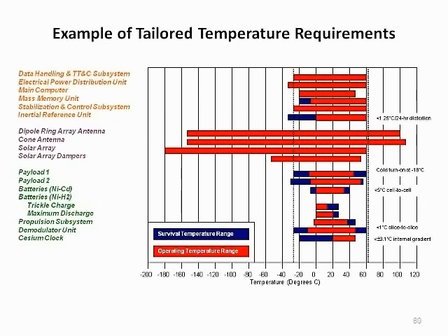As with anything else in life, there are always exceptions. Generalized test requirements don't always work for every type of unit, so waivers and exceptions to the rules are common. Some units, like batteries, would be damaged if exposed to the fully margined or default minimum temperature ranges specified in government test requirements. Hydrazine freezes at 2 degrees C, making functional performance requirements for some propulsion components below that temperature superfluous.